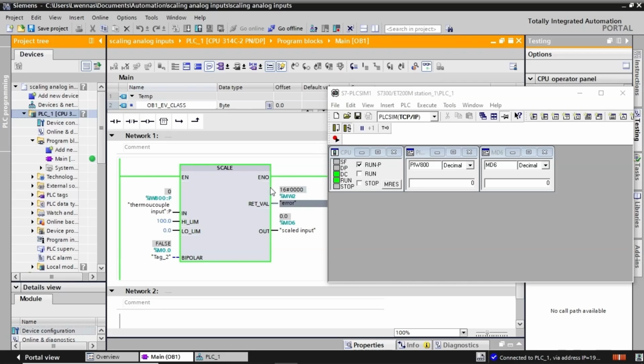As we said earlier in the lesson, one of the scales TIA Portal uses is 0 to 27648. Normally, by setting the thermocouple to 27648, we will get 100 at the scaled value. We change the format of the scaled value to see clearly the result. In reality, the scaling puts the range of the raw physical quantity in a machine language of the CPU and retrieves the value in a double word memory address to be used in the program.